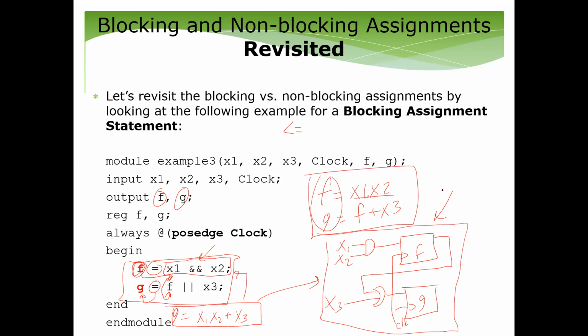Do you think? No. No. What's the difference? Instead of taking f from here, what I'm going to take is this signal here, x1, x2, and I OR it with f. I OR it with x3. So this circuit and the previous one are not the same.